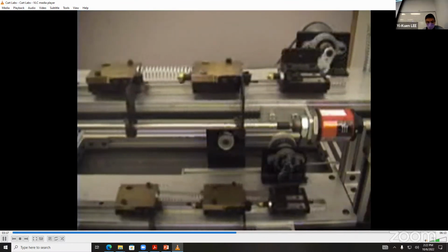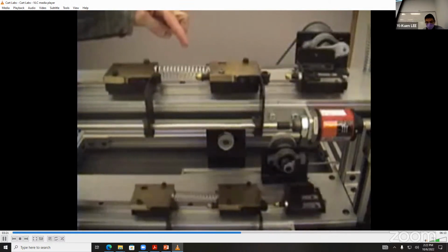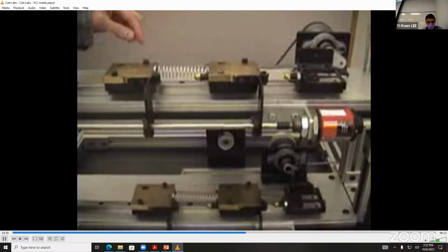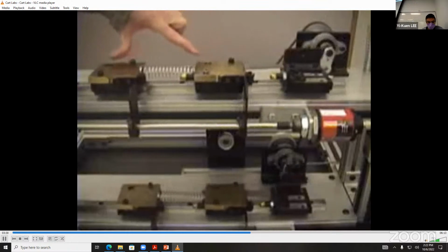So here we're going to look at the frequency response of both systems. Right now they're being driven at a very low frequency, much below the natural frequency. As predicted by a second order system response, the output should have the same amplitude as the input and be totally in phase. So here you can see at the low driving frequency, the output tracks the input and there's no phase difference between the two. It's only a slight difference between the output amplitudes.